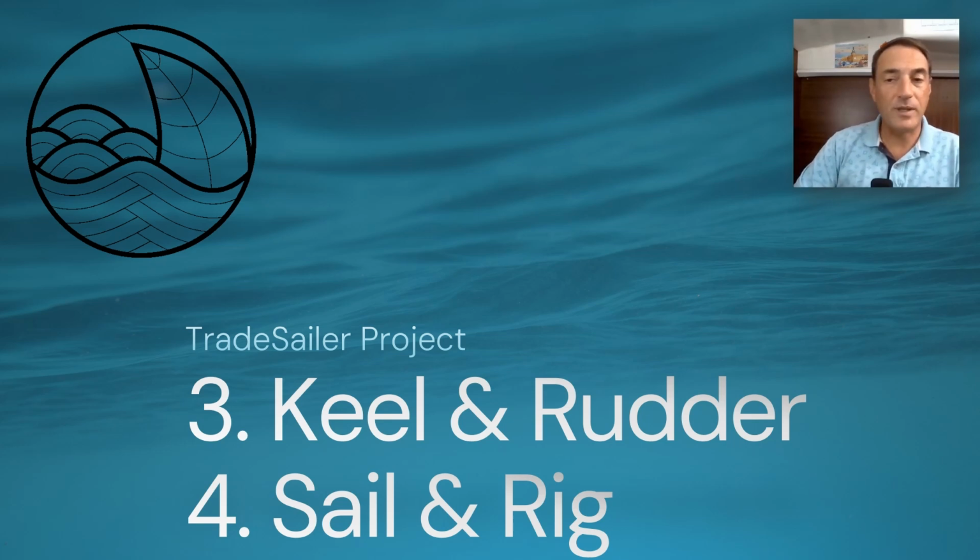And I've done these 2 steps together because we have to balance the two. So we balance the keel and the rudder together with the sail and the rig. They work together. If the balance is not right, you might get a lee helm, or a ship that rounds up into the wind, or a ship that falls away off the wind too much. So the balance between these two is important.